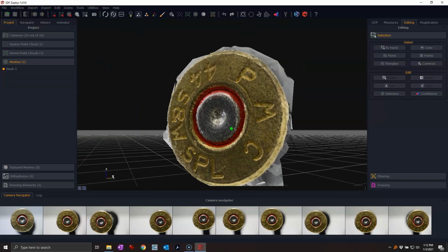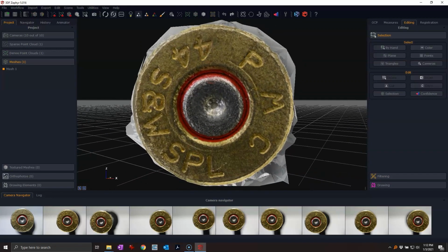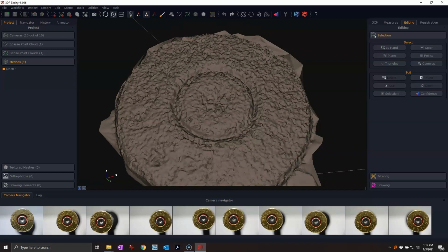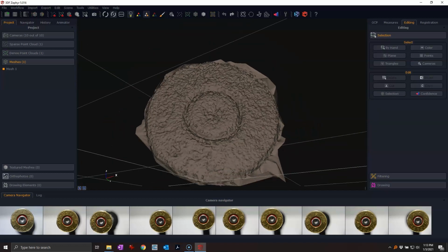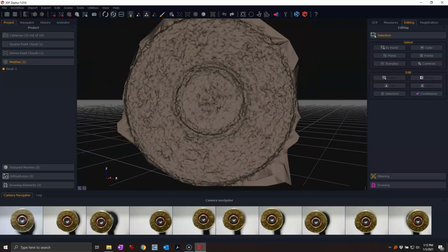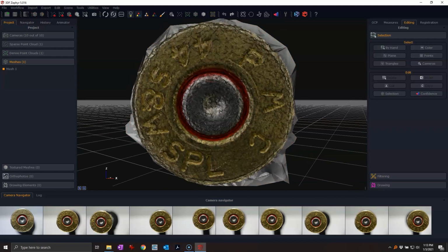So what you should always do whenever you have a photogrammetry model is shut off all the color and just look at the geometry, right? What I want in my case is to reconstruct really good geometry. If you were just looking for a model that looked good enough to the eye, because you just want to use it in a presentation or something like that, then it's not really a problem. You could live with a lot less detail or a lot less quality or accuracy in the geometry. But if you really want something that is going to be useful in terms of measurements, then you need to take that extra step and always inspect the model and make sure that you understand where it reconstructed well and where it failed.